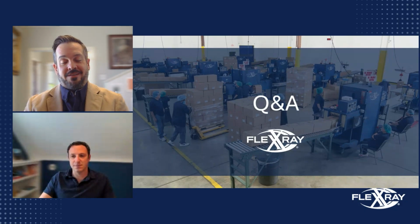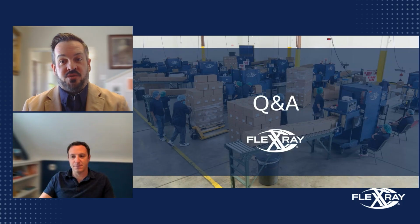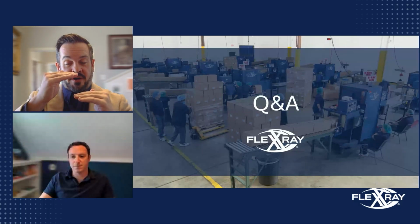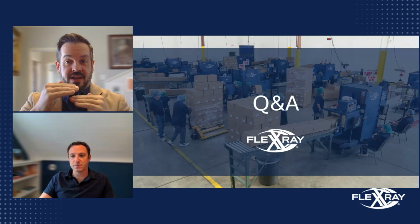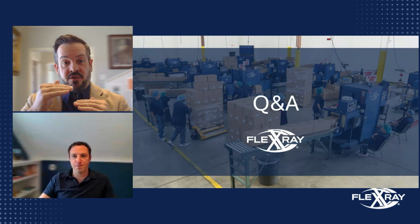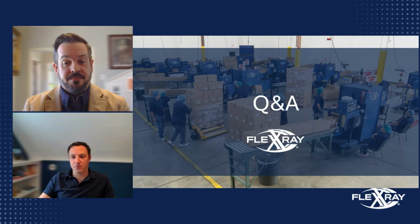Yeah, absolutely. So the algorithm works in 4 distinct ways, and I'll talk about the easiest one first. We're evaluating the density of the product and the density of the foreign object, and we want to try to create enough disparity in that gap to ensure good detection. The more we shrink that gap, there are opportunities for false rejects to occur, or we need to increase the size of the foreign object in order to get that threshold difference back.